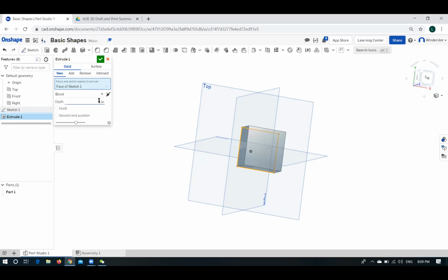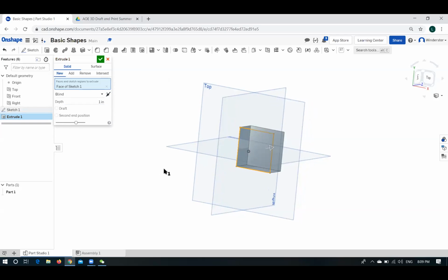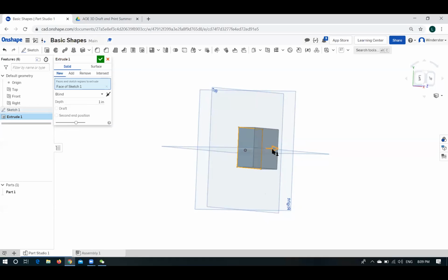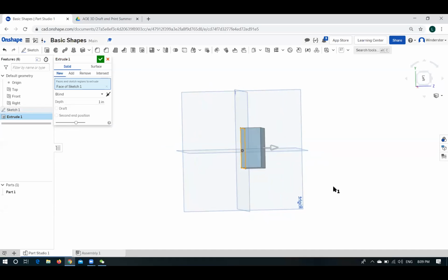So now, if you look down further, there are other choices. How deep do you want this extrusion to be? On the drawing, you can see there's an arrow, right? That's the way the extrusion took place. It's still sitting on the top plane. It extruded toward the top. And you can actually turn this direction by clicking and highlighting. See that when I roll over it, the arrow turns orange. If I click on it, it'll go the other way.